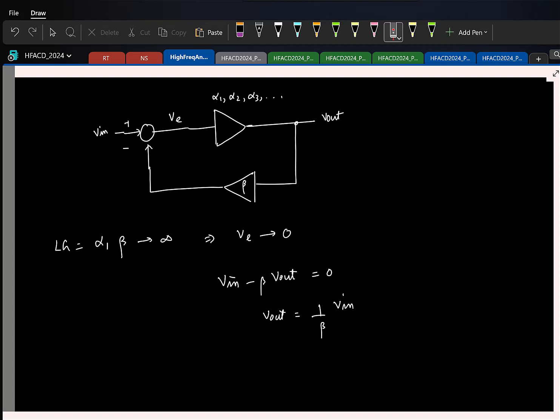And again, that's happening because if you have a large enough loop gain, the error signal reduces. So although the input signal is swinging a lot, the actual signal that is exciting your nonlinear system is this error signal, and that's really small. So which means things will be more linear.